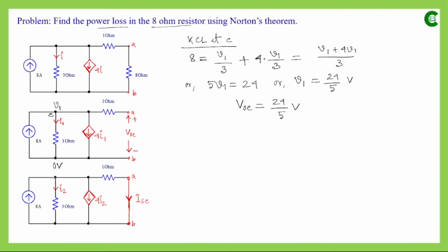Now here this principal node, again if we assume that the voltage or potential value of this principal node is V2 and potential value of this principal node is 0 volt, that means reference node it is, then if we apply KCL again at that node C, then it will be again summation of all the incoming currents. Here this is only the incoming current and all other currents are outgoing current with respect to this node C.